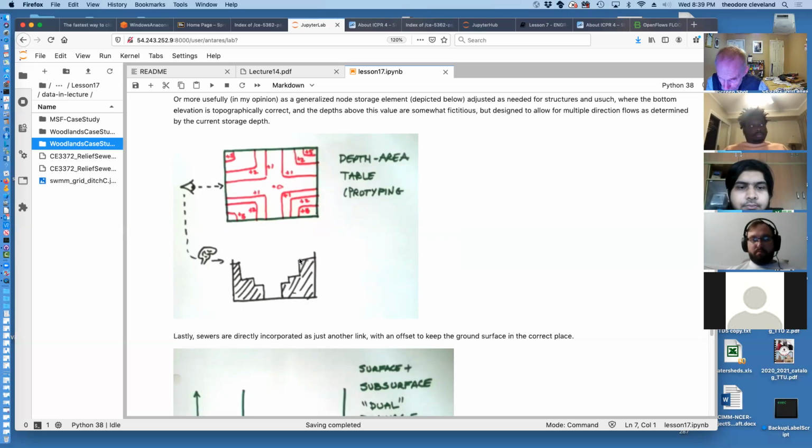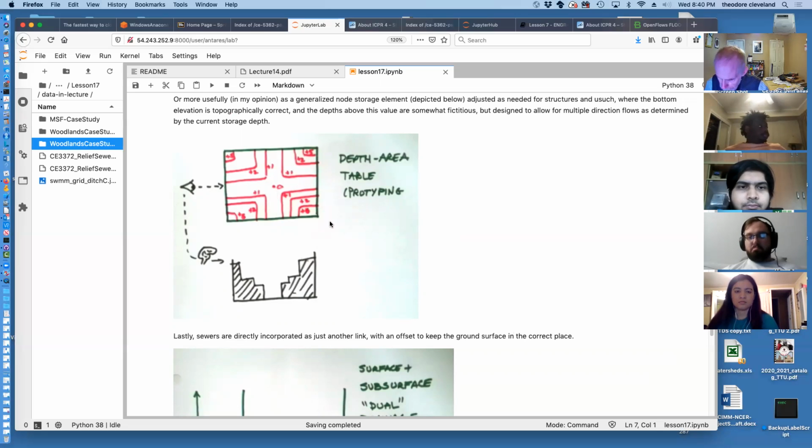And what this has is, if you put 4 of these nodes together, you have pyramids connected to one another. This corner here is the top of a pyramid. So you're representing your whole surface as a collection of pyramids, where the space between adjacent pyramids is where we attempt to capture topographically correct elevations.